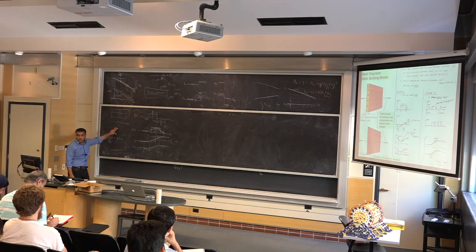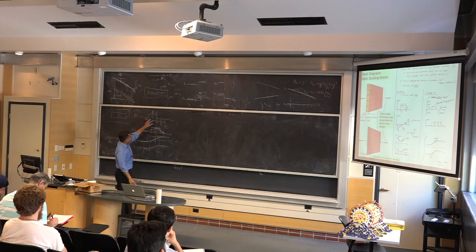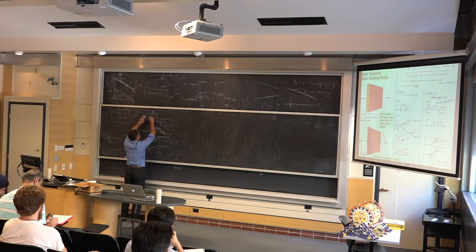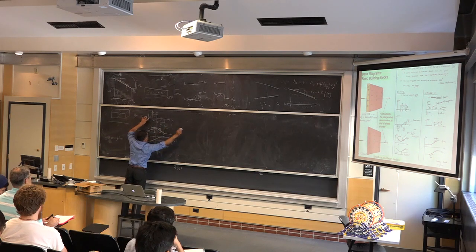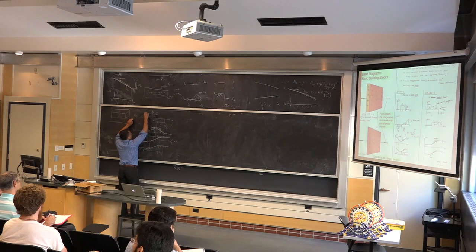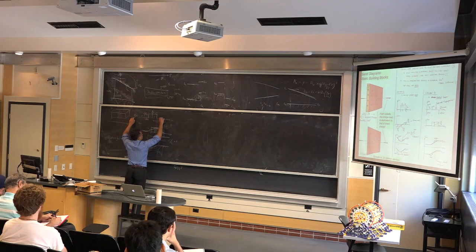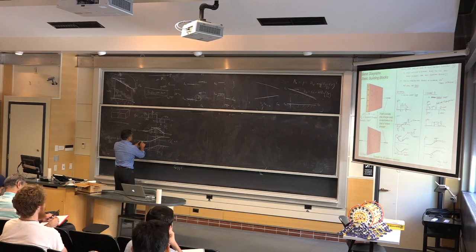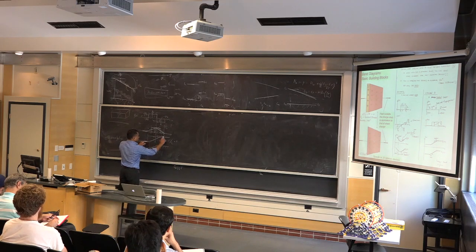That's what we did earlier. Why? Because the charge inside the p and n region at the junction is exactly this. You have, on the donor side, this is n side, this is p side. What you have here is a region where there were donors, but they were ionized because they found lower energy states there. The electrons went up there, and your holes were ionized. So this was Q times the donor density. This is Q times the acceptor density, and then this is what happened. So this is a p-n junction, and in a p-n junction in 3 dimensions, if you create a planar junction, this is how band diagrams will look.